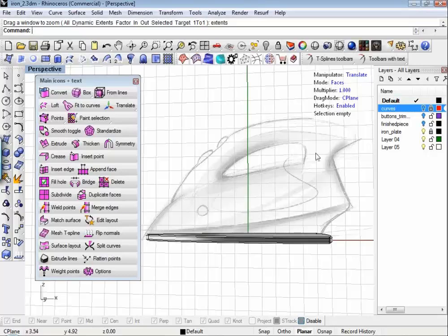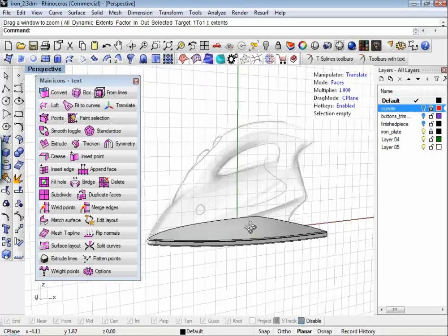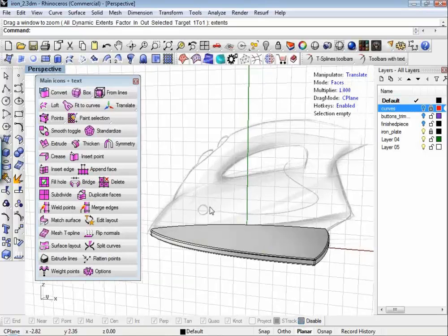Fortunately, T-Splines, the way that it works, is super conducive to this kind of workflow where you're making your aesthetic calls in 3D and designing on the fly. For me, this is a big advantage because to do this object in NURBS, it's certainly not out of the realm of possibility, but as far as being able to make adjustments on the fly, where you can evaluate the surface in real time and mess with it to get it how you want it to look, is sometimes a little bit difficult or time consuming, and making changes obviously requires some rebuild.